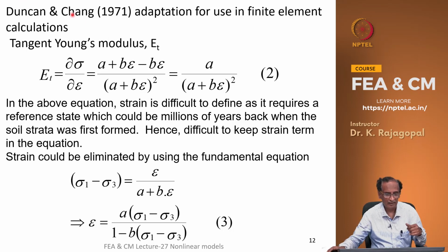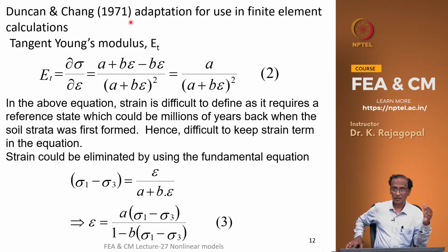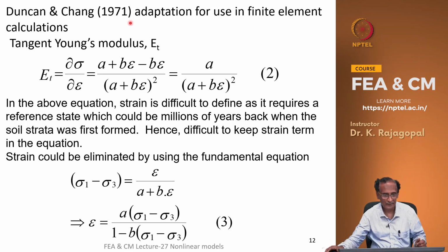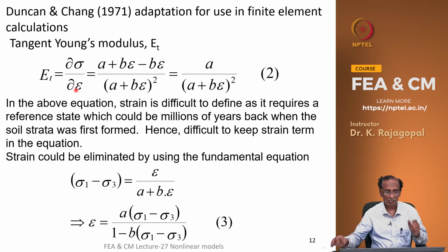Duncan and Chang slightly modified this hyperbolic model to make it suitable for finite element implementation, and they defined the tangent Young's modulus as dou sigma by dou epsilon. This is basically the tangent slope of the stress-strain curve.